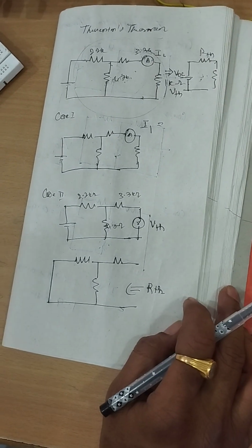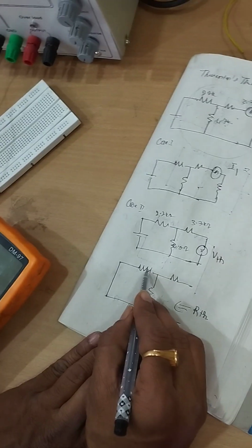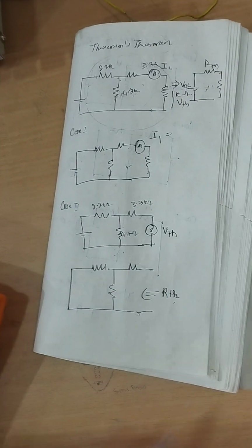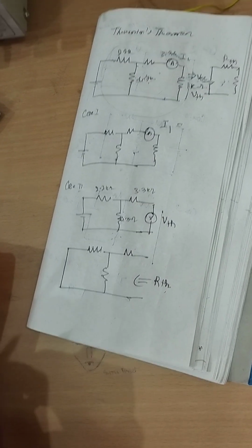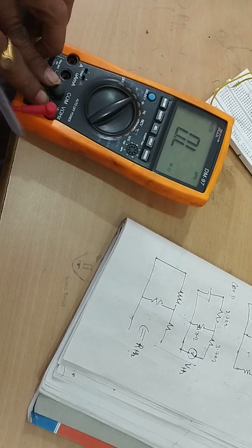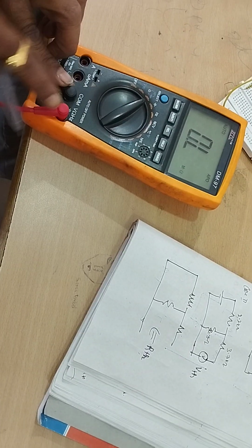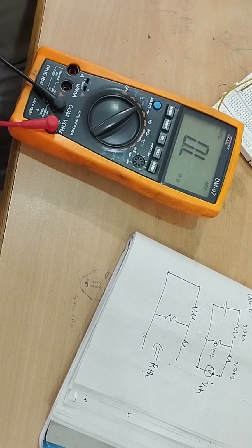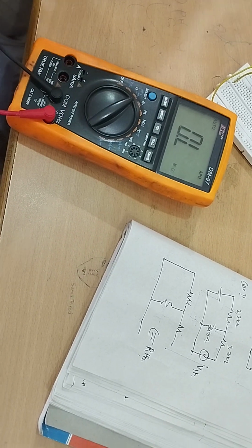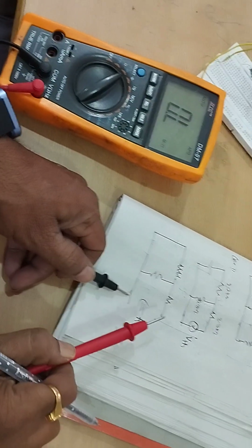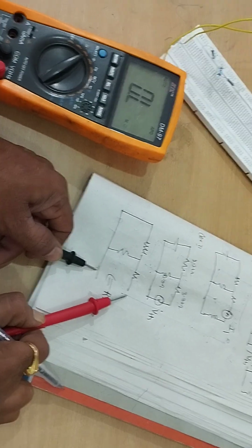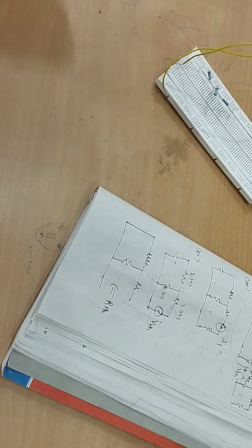So making use of this multimeter, we can measure the resistance value by keeping all the elements as they are. You have to set this multimeter in ohms mode, the common terminal is always common, and put the red terminal in the voltage ohms measurement knob. By using these two terminals connected across these elements, we can take the resistance value. I will show you practically later. So this is the method we will use to find R Thevenin's.